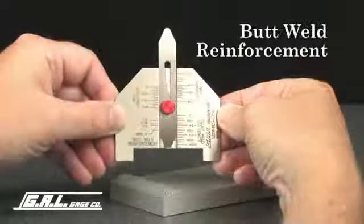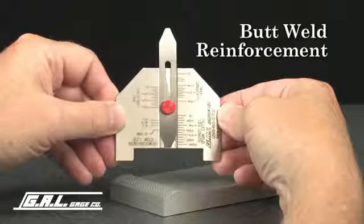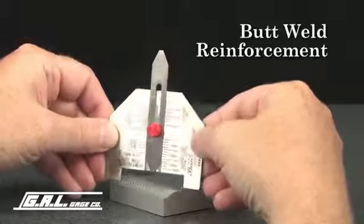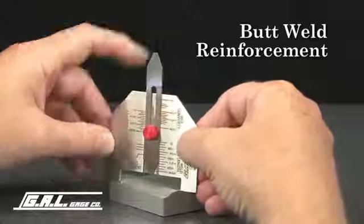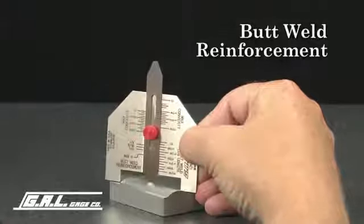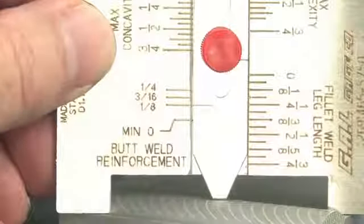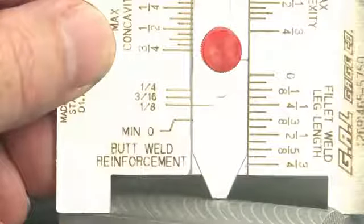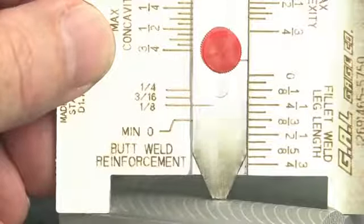Finally, you can use the AWS gauge to measure the reinforcement of a butt weld. Place one leg of the gauge on each plate and lower the slide to the top of the reinforcement. You can measure the permissible weld reinforcement from this scale. This reinforcement measures 1/8 of 1 inch.